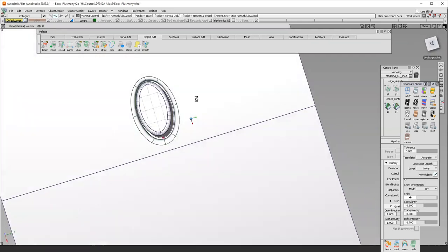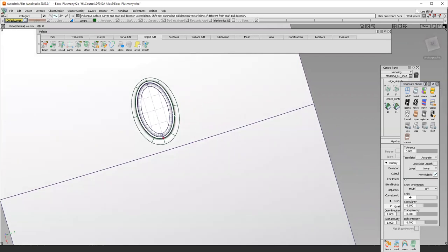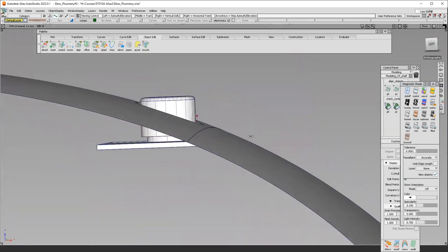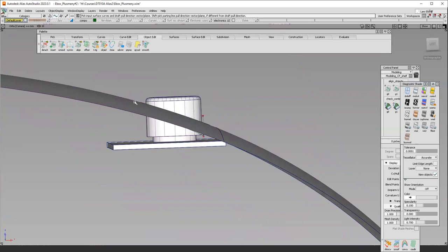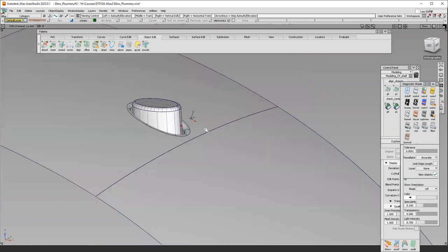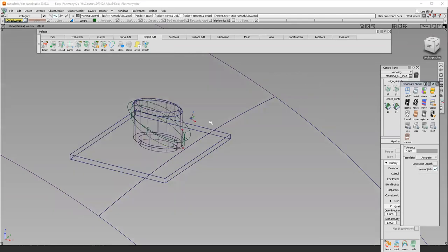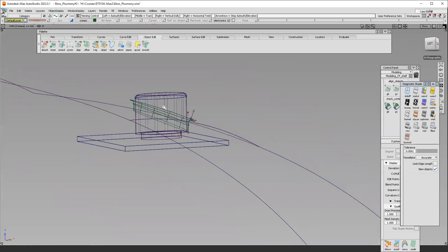We have a really nice, snug fit, evenly around the button right here. So it looks nice. Only problem is that the button is now sticking out, and I want it to follow the contour of the top surface right here. And we can easily fix that by trimming and rounding off the new edge of the button. So let's do that. First of all, I need something to intersect my sidewalls of the button with.